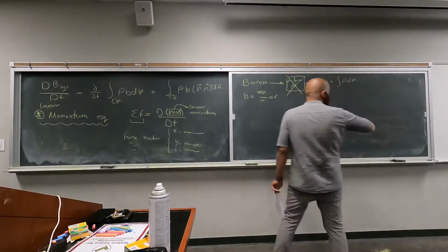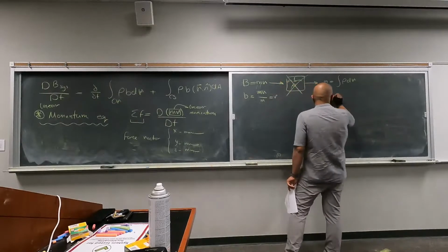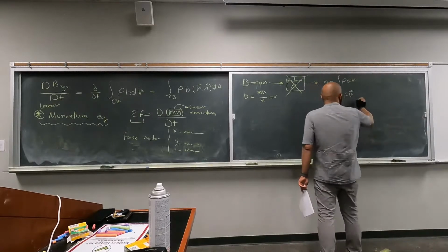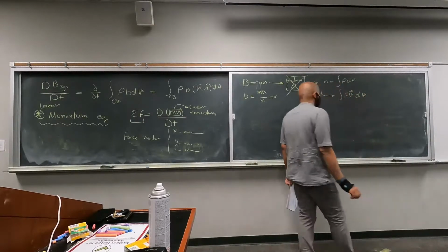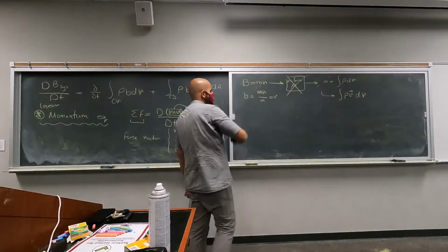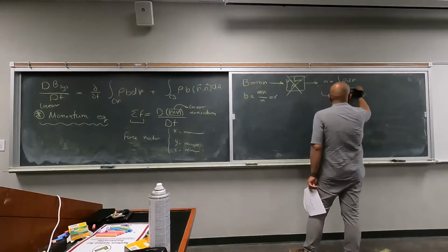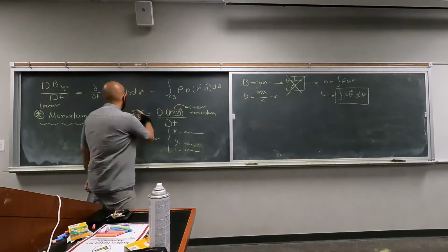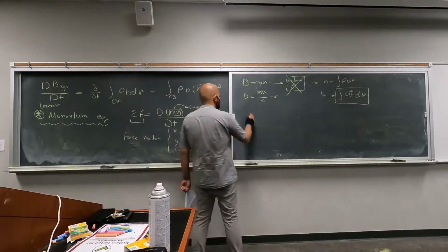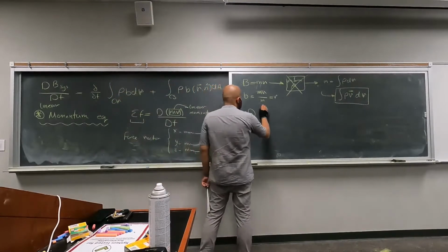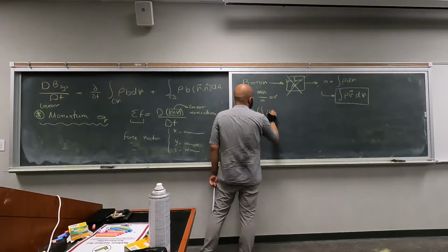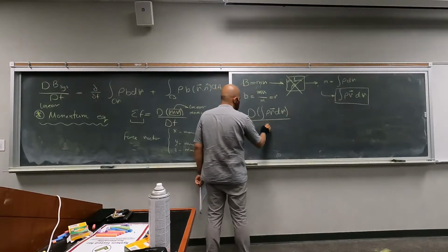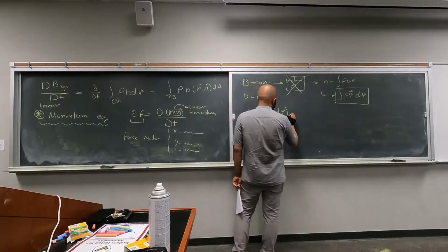Is this clear? Yeah. Which essentially means that your linear momentum is going to be the integral of rho v, velocity, over the volume, right, instead of mv. So this is the linear momentum we are going to use, the extensive property B we are going to use in the Reynolds transport equation. So d(rho v dV)/dt, this is for the system.